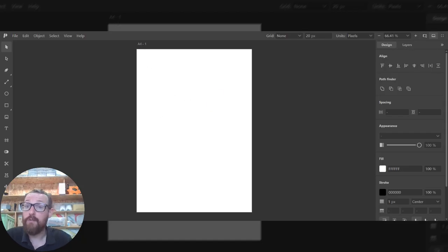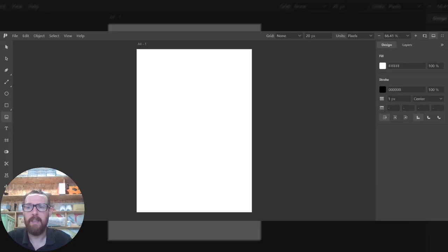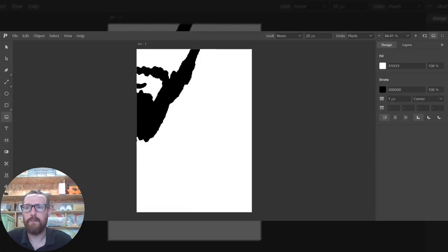Now, what we've done is we've done some drawings on paper and we're going to trace over them. So what we need to do first is we need to bring in the image. So you'll find it here in the Insert Image tab. It's a little picture, a little icon of an image. You hover over it, it tells you it's Insert Image. So let's click on that. And then I need to click where I'm going to drop it. So I'm going to click here and it will ask me to open that image. So right down here, I've got my little logo and let's open up that.